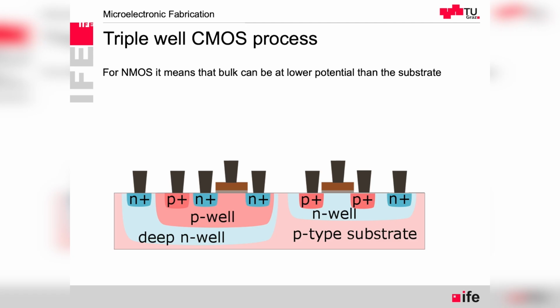For analog circuits in particular, it's difficult because if we have, for example, N-channel source follower, it has the source where the signal goes from the gate to the next stage, and then this source is moving. So the source potential is moving, whereas the bulk potential is fixed. So we always experience the threshold variation depending on the DC level of the signal, and that's something we might not want to have. So what helps us is this so-called triple well process, where we have the P-type substrate,